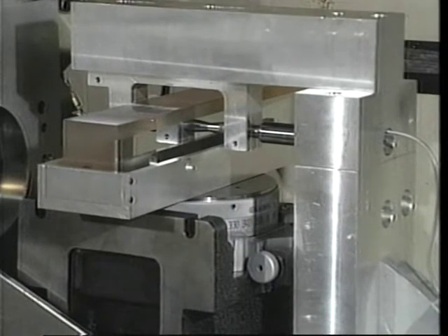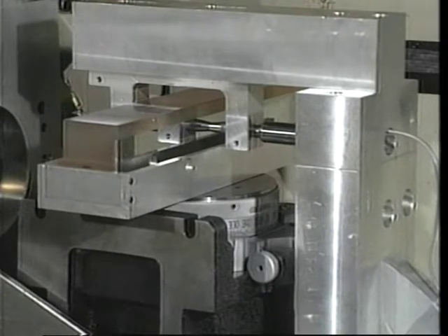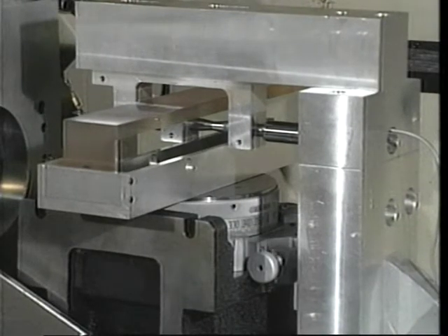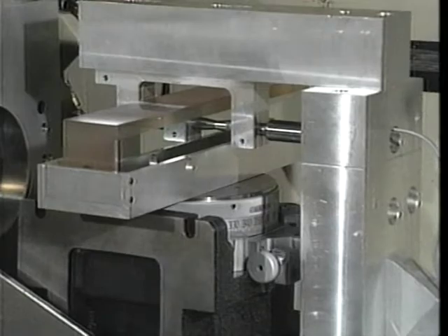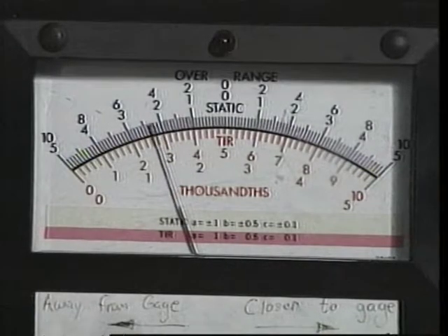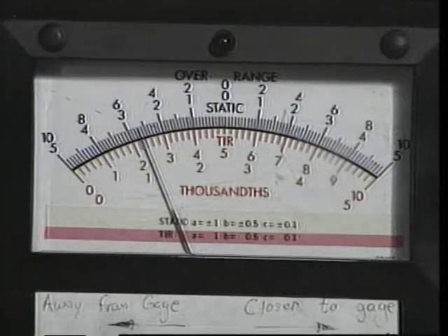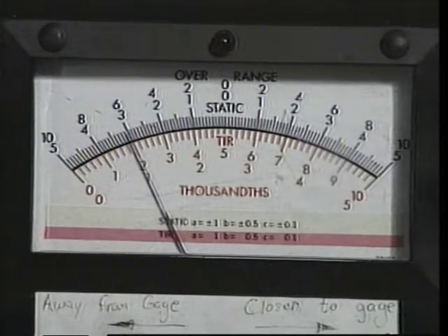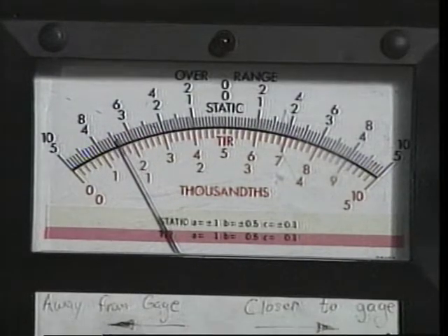Next, the x-axis slide is jogged so that the cap gauge probe is traversed along the straight edge, away from the center of the index. The change in the separation of the probe and straight edge is monitored as the probe traverses until the cap gauge reading goes off scale or the x-axis end of travel is reached.